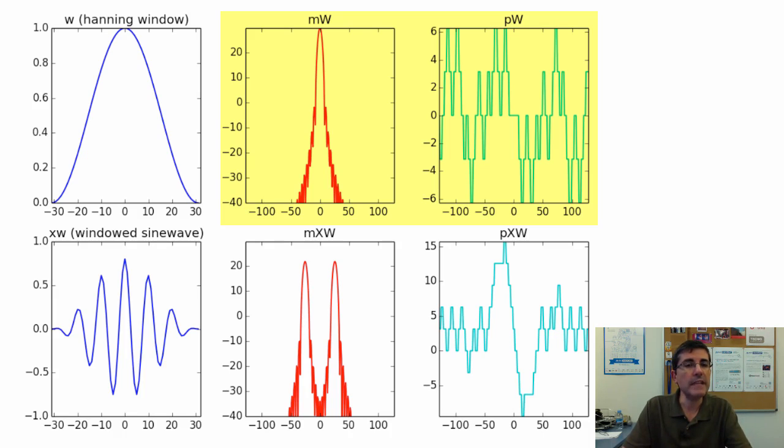And now if we take the DFT of the windowed sinusoid, well, what we are seeing is basically the same shape as the window, but at the frequency of the sinusoid, at the two frequencies of the sinusoid, the positive and the negative frequencies, and at the phase of the sinusoid too. So we have the two values for the two phases with this anti-symmetry that this analysis results into.